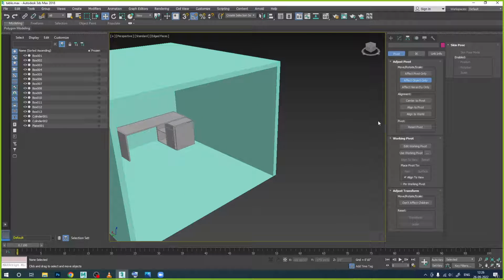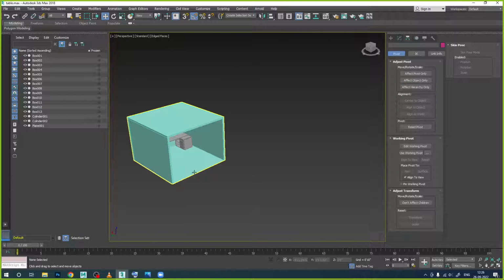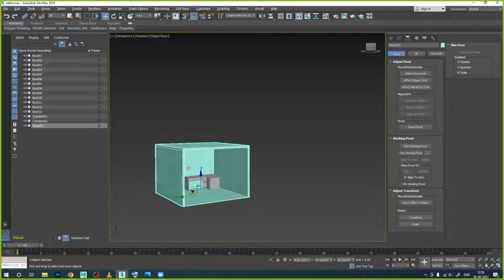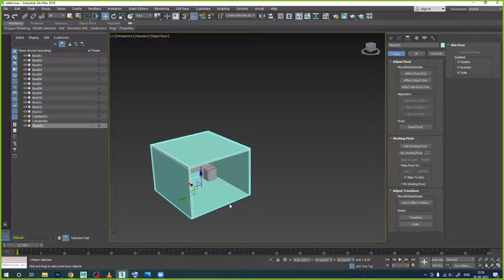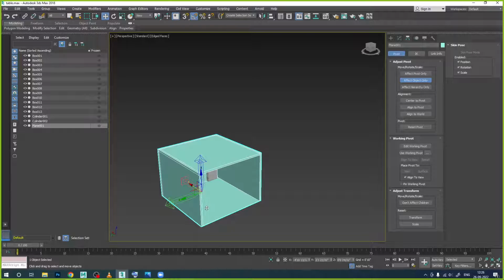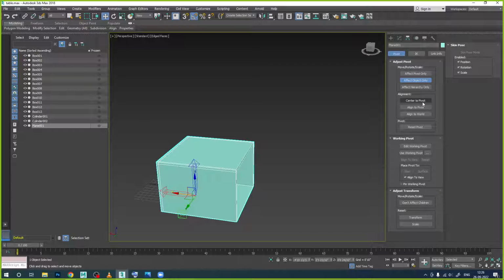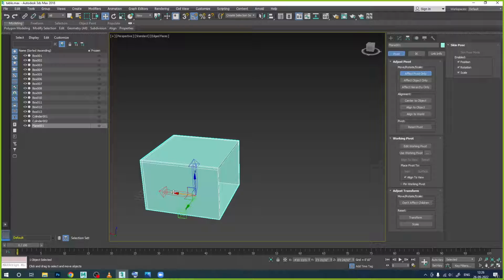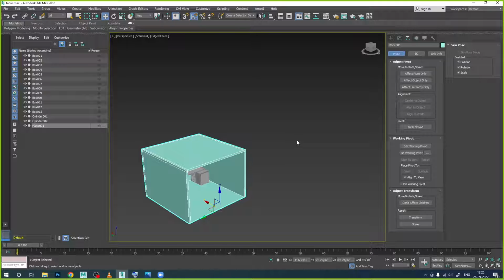One second, deactivate this one. So select this one. For example, this is the object I have in the center, and I want this corner on this one. Effect pivot point, okay, then move this. Sorry, effect pivot point, and now I can move it like this. Then again deactivate. Now you can change the reference point. And for this also we can turn on snap, you can snap it. Snapping can be used for all.